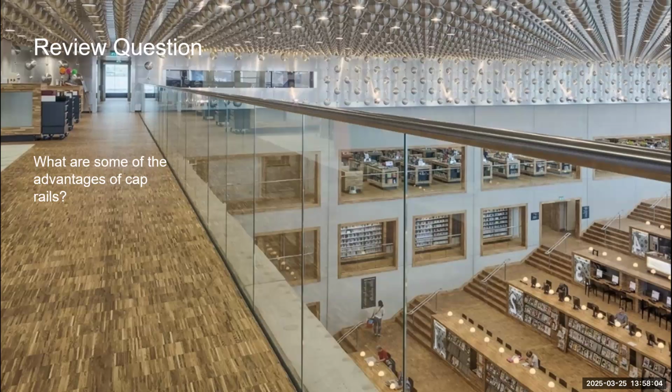And this is where I think an edge protection does two things. It covers the top edge and it helps with glass alignment. Now, there are systems out there like our system or a system with a Q-disc or a taper lock that would allow you a little bit of glass planing to help do that. But another, what I would say, active element in the industry to help with glass alignment on the system is actually a cap rail. That is what I would say is one of the major advantages, in addition to providing some architectural or geometric essence to the system itself.